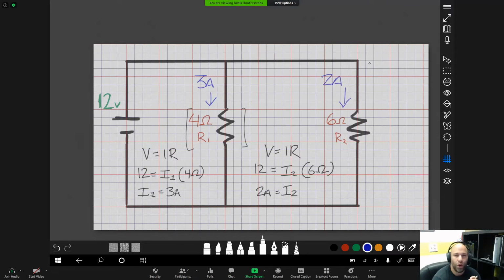Now here's the thing. Without even collapsing this circuit down with total resistance to try to find out what the current or amperage coming out of the battery source is, we can make some really good deductions. For one, we know that the amperage that's coming out of the battery must be equal to what's going into the battery, right? That's going to be a universal truth. We know that we shed 3 amps here at this first junction point. So 3 amps goes away. So whatever this amperage coming out of the battery is, we lost 3 off the bat.